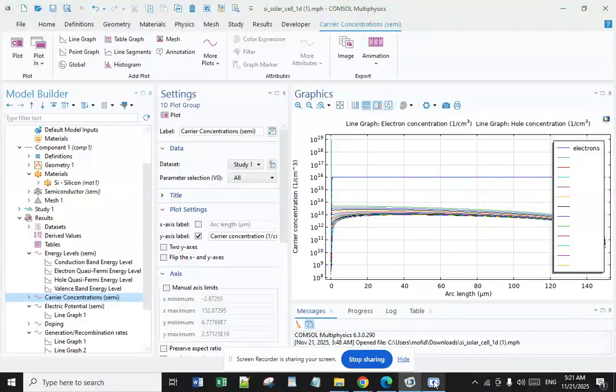These highly doped layers help to separate the photo-generated charge carriers from the bulk of the crystalline silicon wafer. The trend in the photovoltaic industry is to reduce the thickness of the wafers to 250 micrometers and to increase the area to 20 multiplied by 20 centimeter.